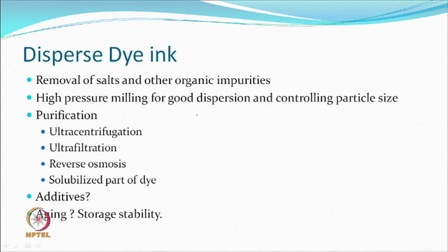Then it is not water soluble, and therefore you will be doing a lot of milling to reduce and control the particle size. That is an important part. Then remove everything else, keep the particles on one side. Anything called a solubilized dye, maybe use ultrafiltration, reverse osmosis. You are going to be using all these techniques, therefore you are increasing the cost. And then of course, at the end you will be adding some additives, as we said, because you are also interested in storage stability, because dyes may have to be stored for months and years before they are actually used, and this also is tested.